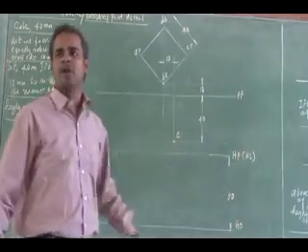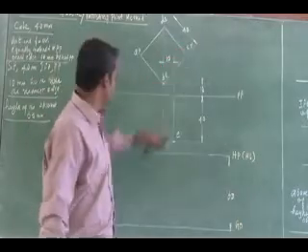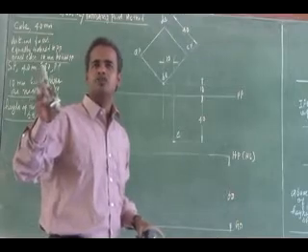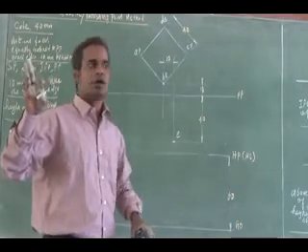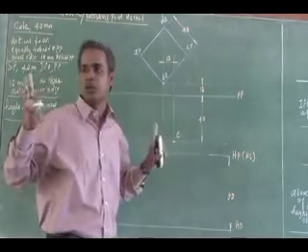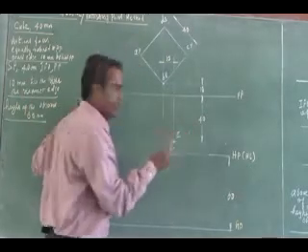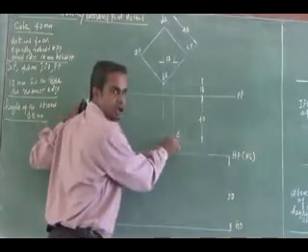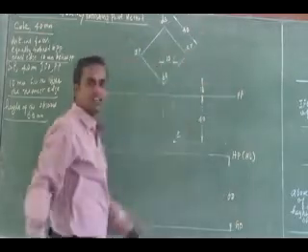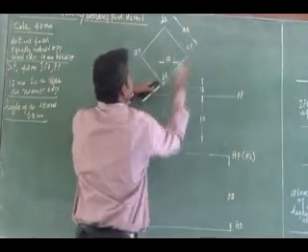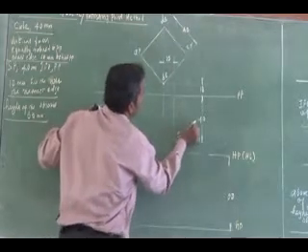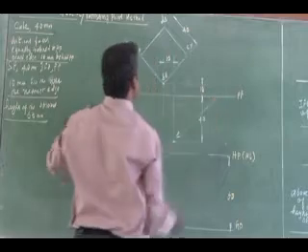How to obtain the vanishing point? Listen all of you. How to obtain the vanishing point from the station point? Always, on which plane does the vanishing point fall? The horizon plane. So I have to get my vanishing point on the horizon plane. That is for sure. Now to get that vanishing point, from the station point in the top view, draw a line parallel to one face which is inclined to the picture plane. Which face? That is the BQCR face. Parallel to that, I am drawing a parallel line.